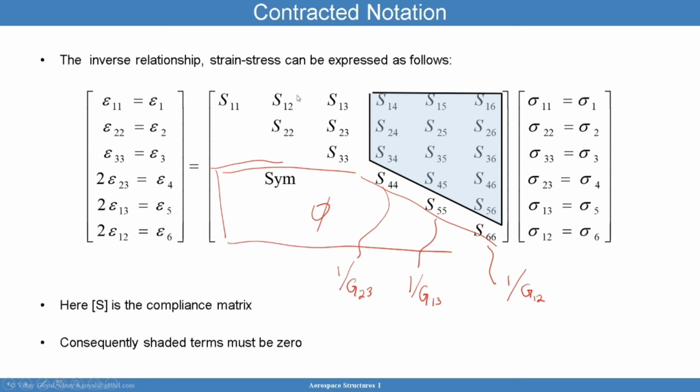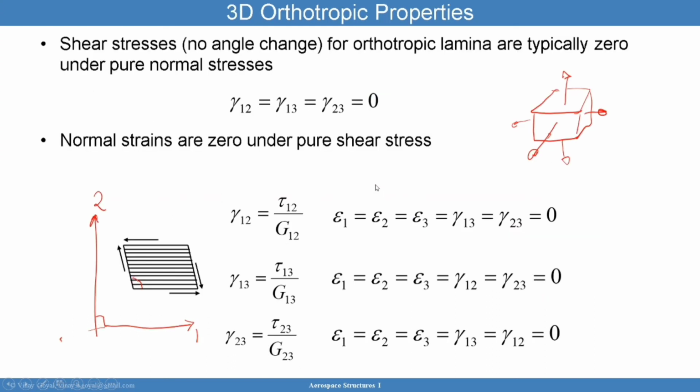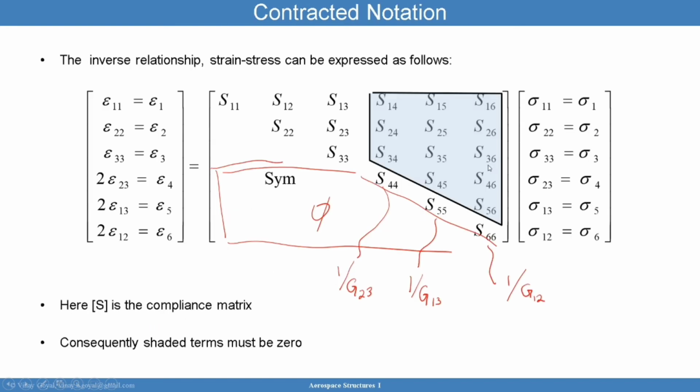And you can see here that this is 0, that's 0, and that's 0. So these last 3 shear stresses don't come even into play. So the normal strain only depends on what's going on with the normal stresses. It doesn't interact with the shear quantities, which is exactly what we wanted. We wanted to come up with a relationship where if I apply shear strain or shear loads, it does not cause a normal strain. And we've seemed to do that by setting all this equal to 0.